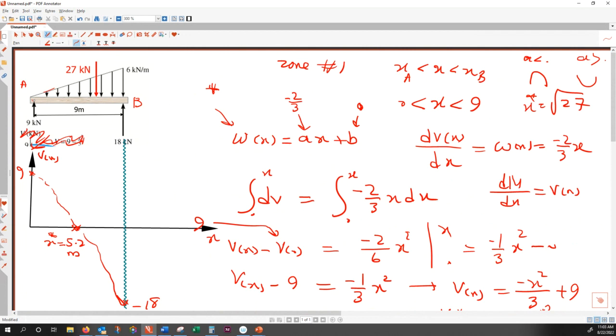Tapiva, what is m of a? Bending moment evaluated at point A. What is it? Daniel? Damien? Damien, do you know what bending moment at point A is? Ben, what is the bending moment at point A? Yes, that is 0, correct? Thank you, Ben. Because this is a pin support, the pin support cannot withstand any bending. So therefore, m of A is equal to m of 0, that is equal to 0. Thank you, Ben, for that.